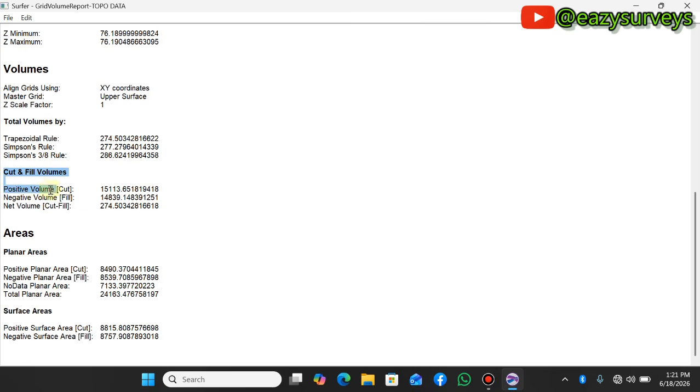What this cut and fill volume report simply means, in layman's understanding, is that based on my design level surface, the amount of cut is greater than the amount of fill. That simply means there will be excess material left after I cut the highest part of the elevation across my project site.